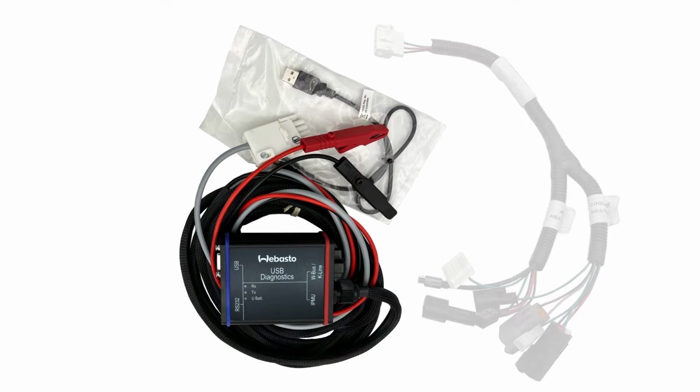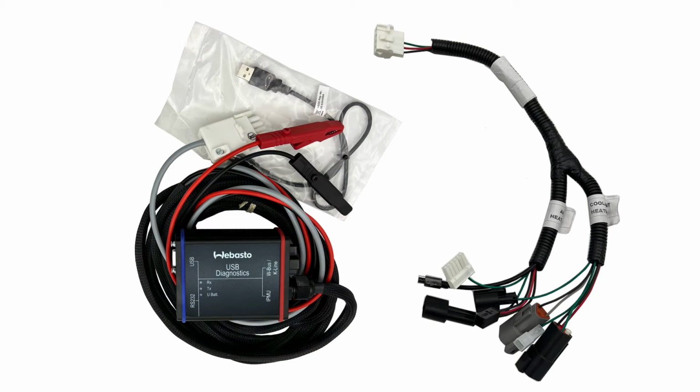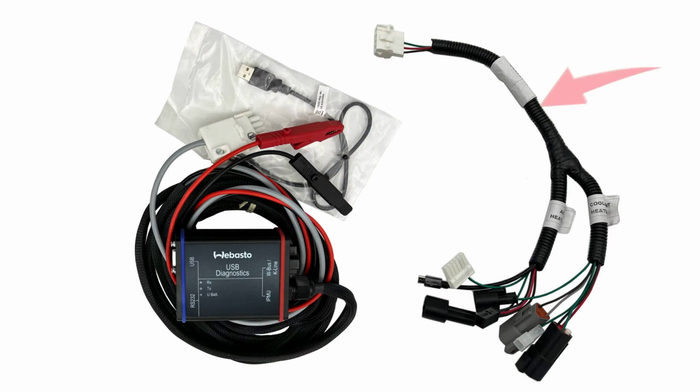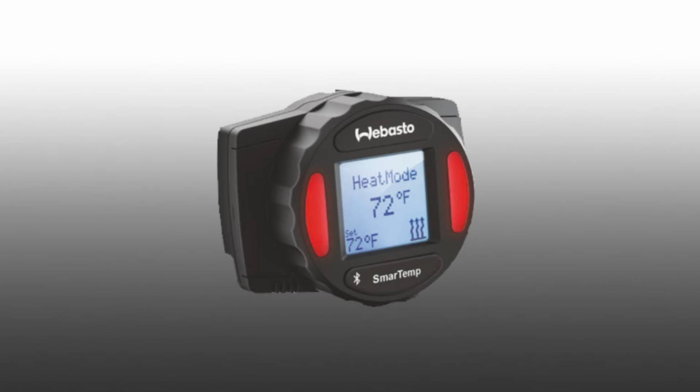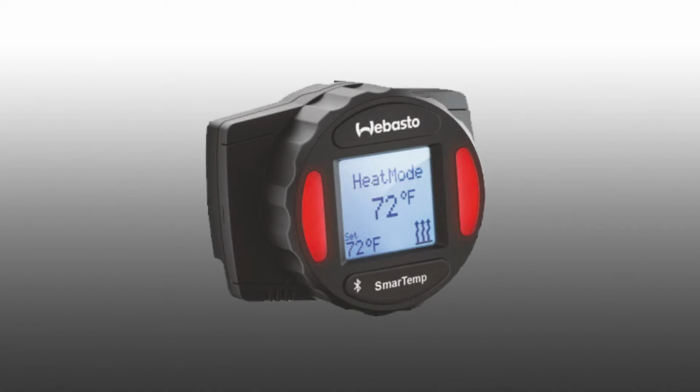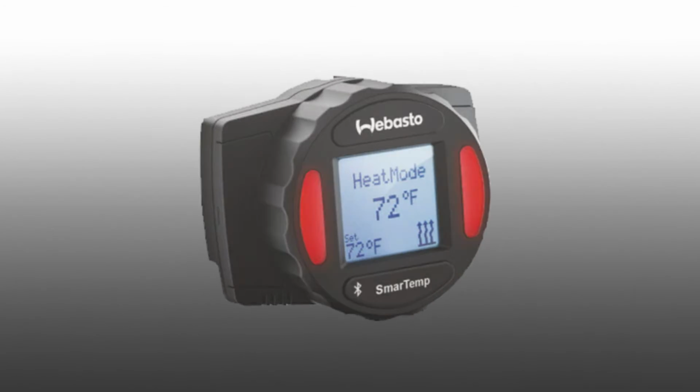And finally, you'll need an adapter to interface with the heater you're working on. You can find this part number in the service parts list for each heater model. You'll also find a multi-adapter that allows you to connect to any PC Diagnostics capable heater with just one part number. If you have a heater equipped with the SmartTemp 3.0 timer, you'll need to unplug the SmartTemp in order to clear the communication bus for the Webasto Thermotest program.